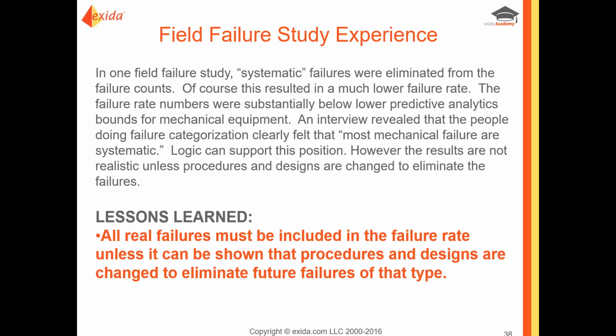There is what's called a taxonomy in many of the data collection tools, which list a set of failure modes for each product type. At exida, in the FMEDAs, for example, for sensors, we published more than just safe and dangerous. We published fail high, fail low, fail diagnostics, and of course fail dangerous, which is primarily frozen output. So we don't pre-categorize everything the way some of our competitors do.